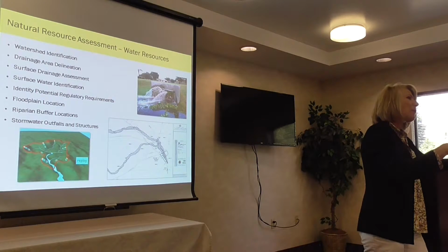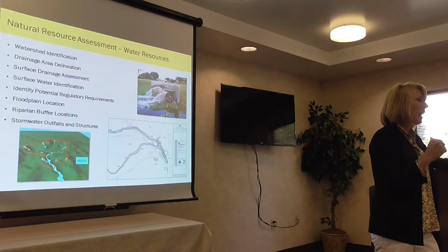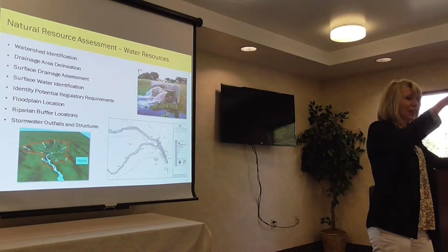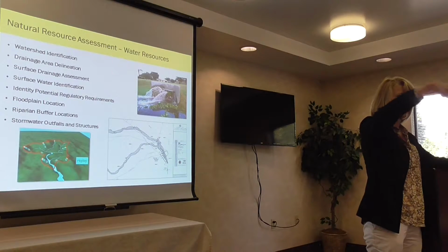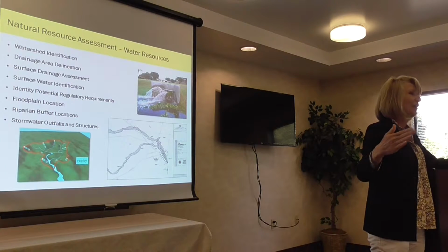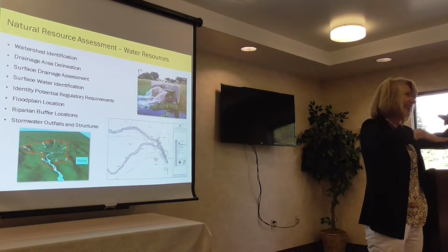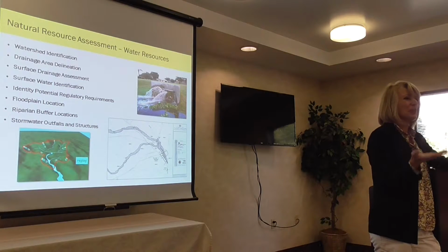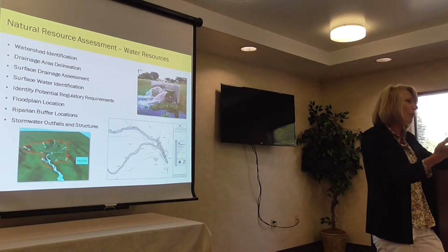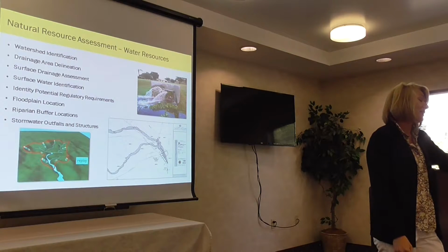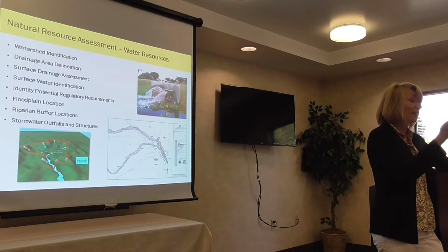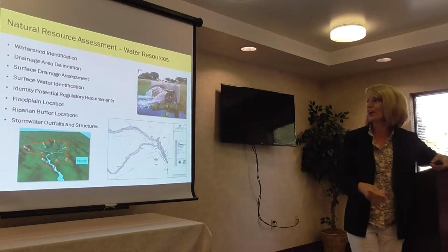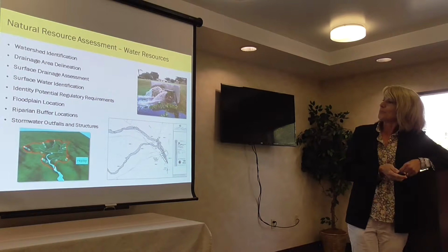Well, what we realized when we went back and started to look at all the old historic maps was that that entire area was a huge wetland. And there were all these trenches and all of these streams that basically created this grid system throughout the entire town that were flowing in all different directions. So it went against what you would really look at as how the drainage would go in the watershed. But you really had to understand that this entire site at some point or another was a wetland, and all of these, what look like streams, are actually trenches to drain it.